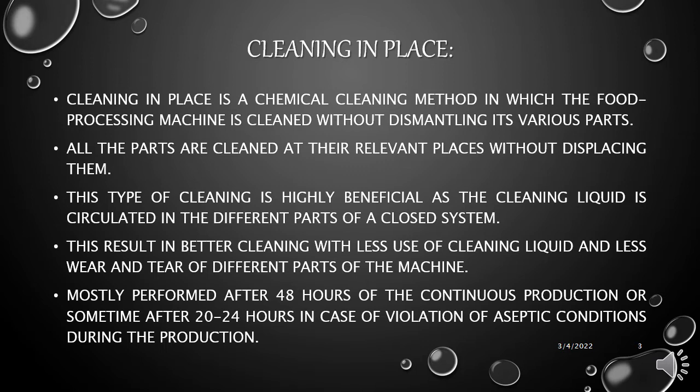CIP is mostly done in continuous production after 48 hours. But in case of violation of aseptic conditions during the production, we can also do CIP after 20 to 24 hours, after batch production and before starting a new production.